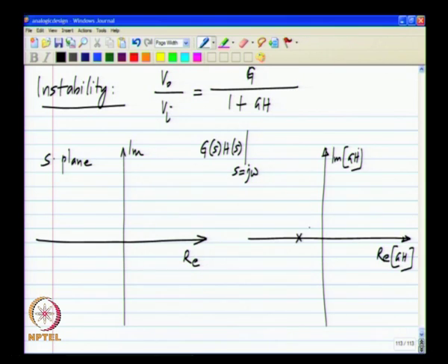Like I said rather vaguely, the stability criteria involve avoiding the loop gain being minus 1. So, this minus 1, 0 is a critical point in this whole technique, and what the Nyquist criterion states is that the plot of the imaginary part of the loop gain versus the real part of the loop gain should not encircle minus 1 comma 0.